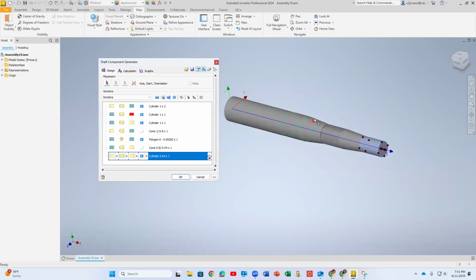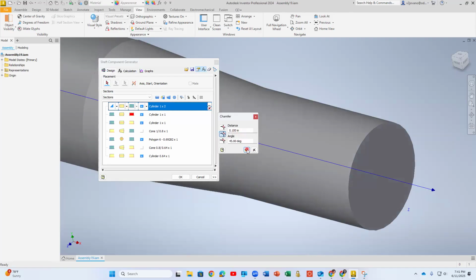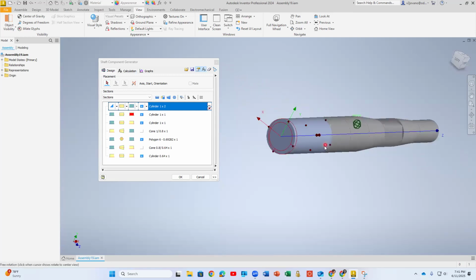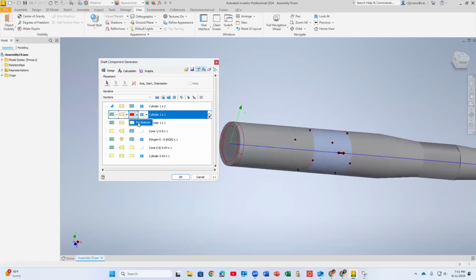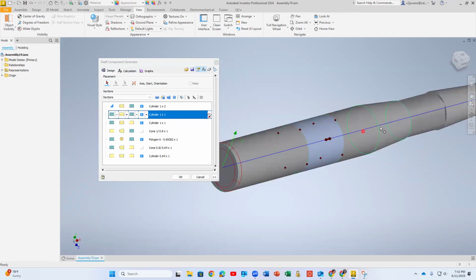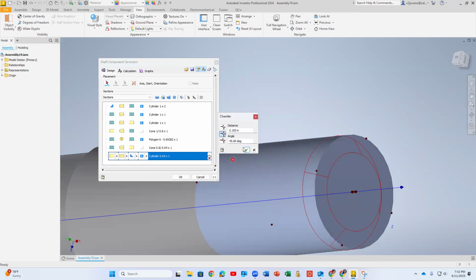So, you can add different sections like this, and make cylinders 1 by 1. And at the end you can add how the shaft ends. So for example, if I switch this to chamfer, and I put some chamfer at the beginning and at the end, you will see the difference. No feature. So you see, this is our first. I added the chamfer here. It's kind of impossible because they're all the same shape, but maybe at the end we can also add a chamfer here, because when we're machining something, it's really hard to make something with no feature at the end. So just put a chamfer, because usually that's how things look when we do machining.